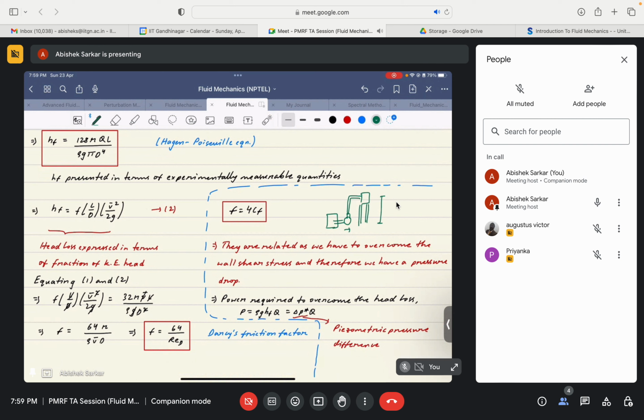So this is undesirable. If these viscous stresses were minimal or didn't exist, then the power required to pump would only be the power required to overcome the static pressure head, right? So in that case this is undesirable, and thus the significance of these viscous stresses comes in applications where liquid has to be pumped from a lower potential to a higher potential, and also when the liquid traverses long distances from the source to some other sinks.